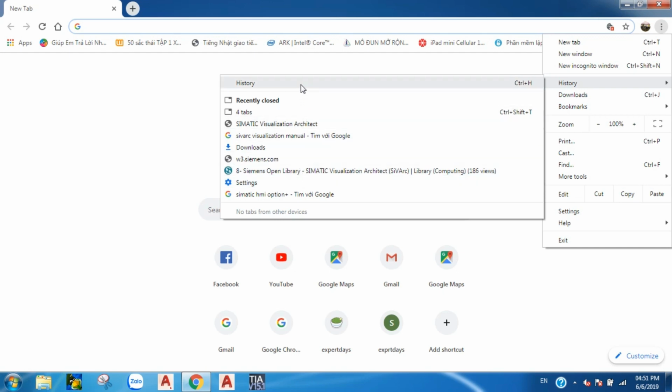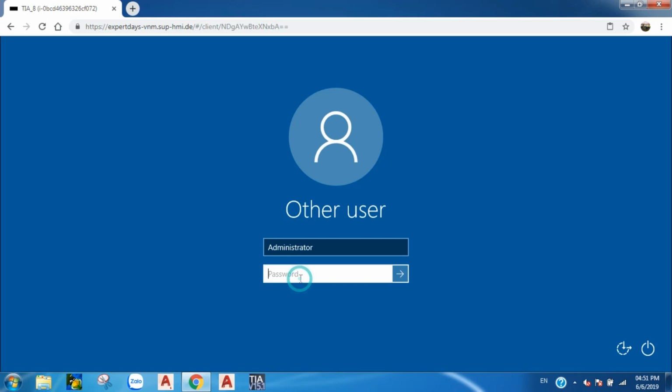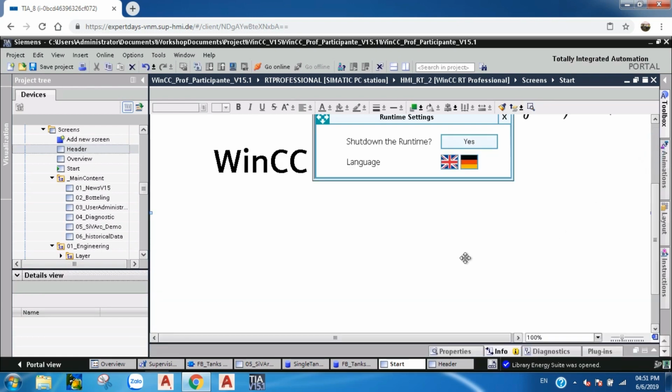So I created an analog alarm in here. I can see there is no tag configured because it's my template I want to use. And I again have my plugins tab here. For my alarm, again, I have to define a name. Again, you find here the symbolic name of my FB. In that case, I want to generate three alarms: one alarm for single tank 1, one alarm for single tank 2, and one alarm for single tank 3.